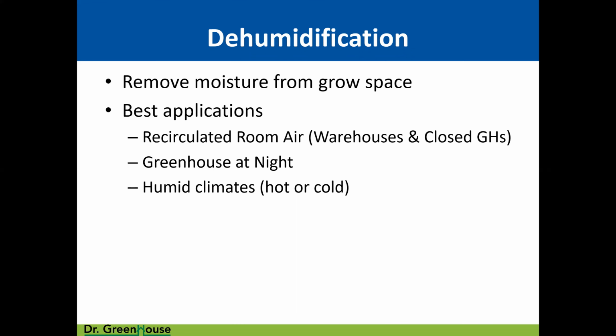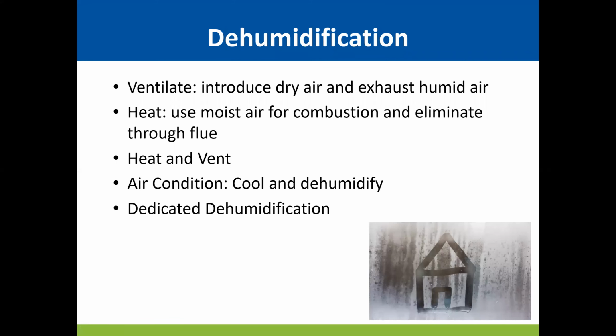Okay, dehumidification. We are removing moisture from the grow space, okay? Best applications when we're recirculating the room air and we're not bringing any dry, fresh air from the outside. Greenhouses at night. When it is cold and dry outside, we can relieve some of that moisture. And of course, if you're in a humid climate, and we want to remove moisture. Okay, so there's a few different strategies, whether you're in a greenhouse or what I'm going to call a warehouse type environment. We can ventilate, okay? That's the simplest thing to do, lowest energy, lowest cost strategy.